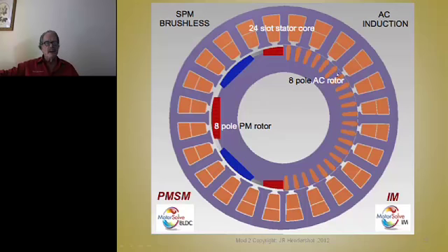So I'm constantly, since the poles are slipping, they're not glued on the rotor and not rotating with the rotor, the effect of the current flow in the bars, so the last bar and the first bar are constantly having the current reversed. It's either going into the screen or out of the screen. So that's how it creates the slipping poles.